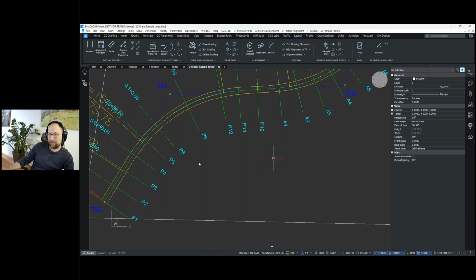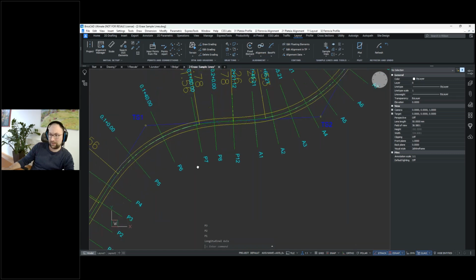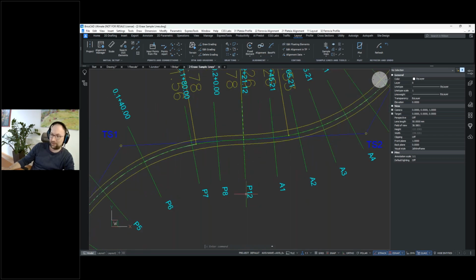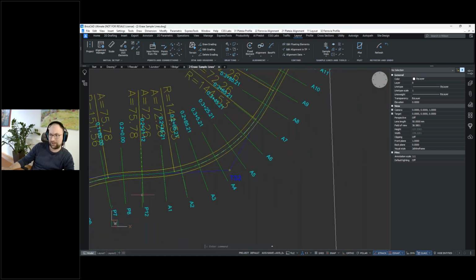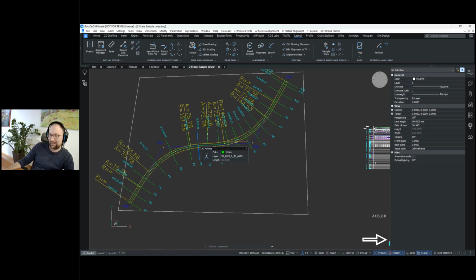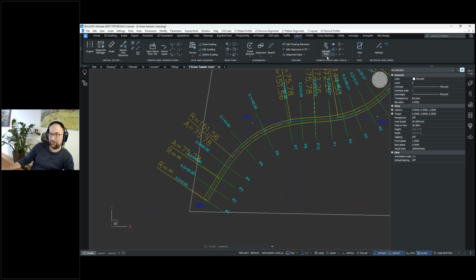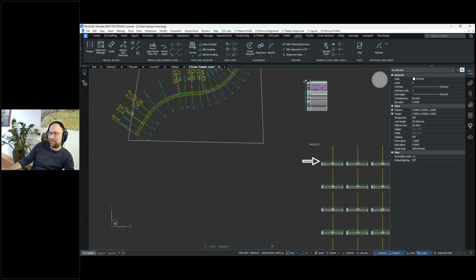But once you delete it, all other sample lines that have the same prefix will also be renumbered. So this will not change the fixed names, or this will not change the other numbering that you have maybe. Yeah, you will not have to renumber them with some other command.